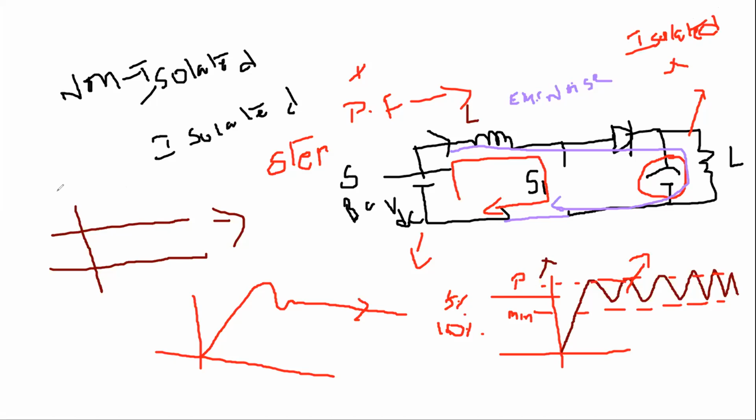But if you need a low voltage, your mobile battery needs 3.8 to 5 volts. Your laptop may need around 12 volts. So you are easily converting 230 to 12, right? You are converting AC to DC, then again stepping down the voltage levels. In all our electronic gadgets, we are using non-isolated DC-DC converter topologies only. But to charge an electric vehicle, automobile companies prefer isolated DC-DC converter topologies.